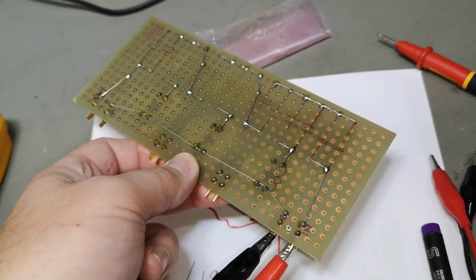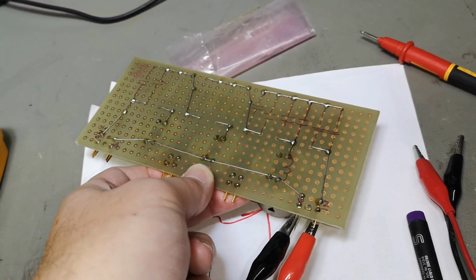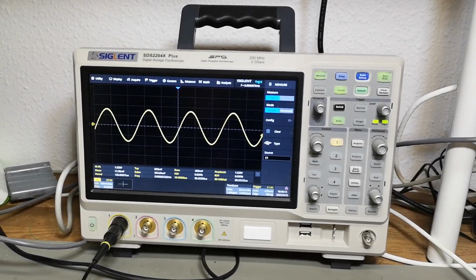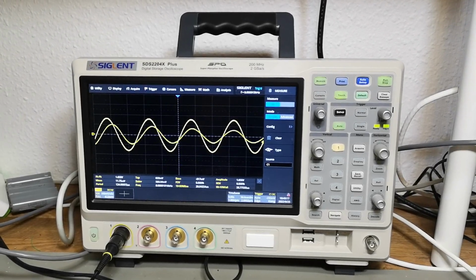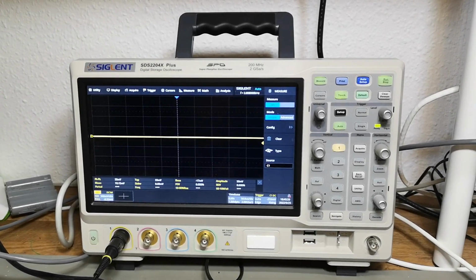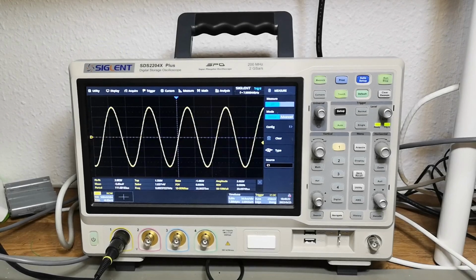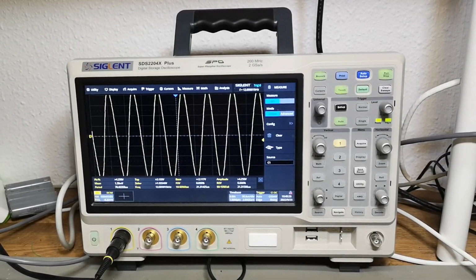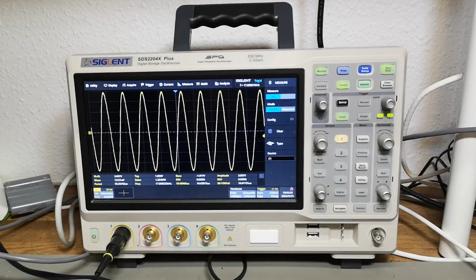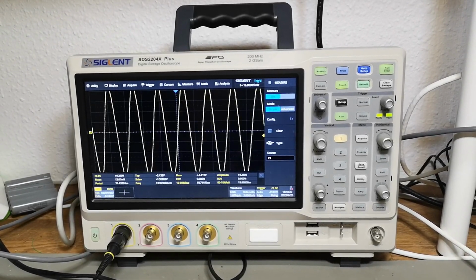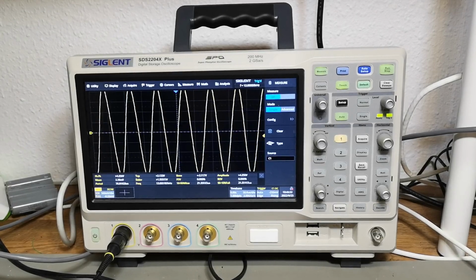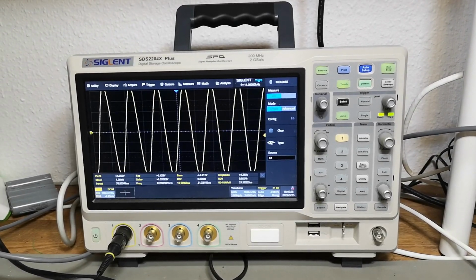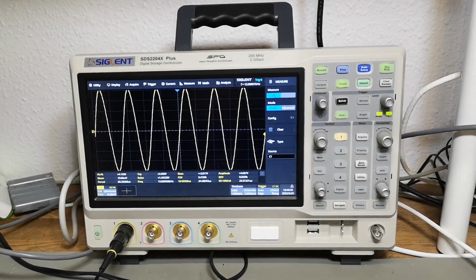So at what frequency is this working? Let's have a look. So this is 8 kilohertz. Let me just step 1 kilohertz to make this real fast. 7 kilohertz input, 8 kilohertz, 9, 10, 11, 12, and then it goes a little bit like that, right? So I think you can see the peak here, right? So I think this is a 12 kilohertz high pass filter.